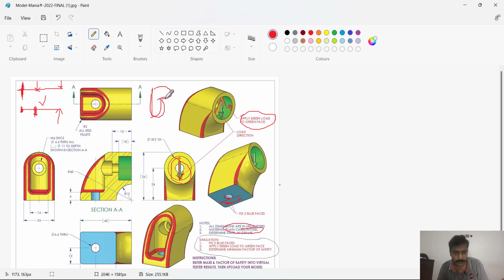So this is the area which is going to have more stresses. How can we add more support here? For example, we can add a rib like that, which is going to support this stress. Here we add a rib, and then we run the analysis and again see the values of the stresses, whether it's failing or not.